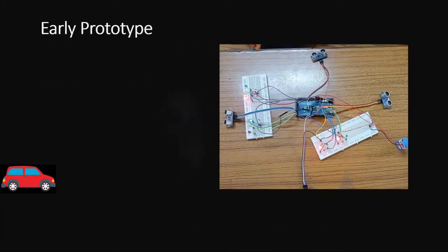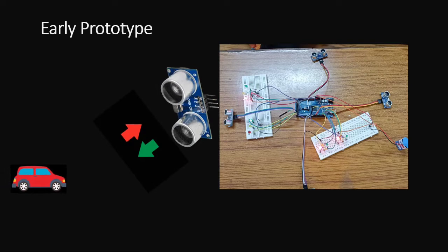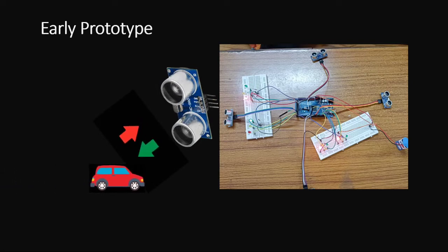To develop this solution, we have used the Arduino Mega 2560 chip, which is based on the ATmega2560 microcontroller, which will control the flow of traffic signals according to the data sent by HC-SR04 ultrasonic sensors. Each sensor is provided to each traffic signal lane to check for density by receiving the ultrasonic sound wave sent by the sensor itself. This sensor is effective for a range of 4 cm to 400 cm of distance from sensor to object. Now, the requirements of this project are as follows.